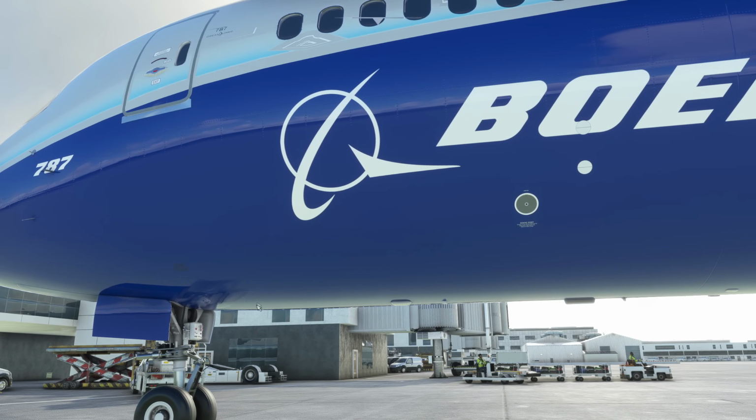Now, there is also a forward outflow valve over here, which is not modeled. That is where the air is let out, and that valve is controlled by the pressurization system to make sure that the cabin altitude stays at a sensible altitude. Interestingly enough, on the 787, it pressurizes to a lower cabin altitude than previous aircraft. So it's about 6,000 feet on average, even if you're up at 43,000 feet, it can do that.